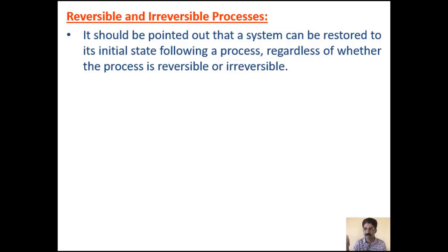So some friction will be there between the piston and the cylinder. Because of that, some heat will be generated, which will be absorbed by the working substance. So its internal energy content will not be exactly delta E, but delta E plus this frictional heat energy. Now when you do the reverse process, with W amount of work, the Q amount of heat will not come out. So you need to do some additional work to remove this extra heat.